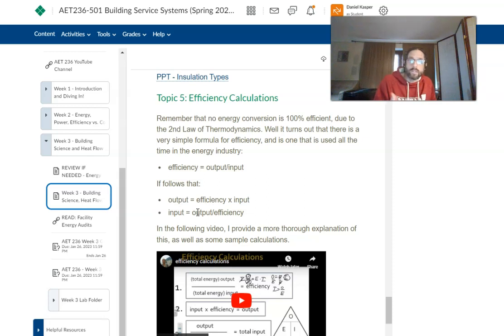And so that's where this all ties together: you have heat that flows through a surface, and decreasing the U value or increasing the R value will slow down that heat, but it's still going to travel through all these surfaces. So now I have all these surfaces all over the house, right? So I have walls and a roof and basement and so forth. So there's heat flowing through there. So you lose heat from inside to outside, and then you have to replace it to continue to keep it at around 70 degrees.